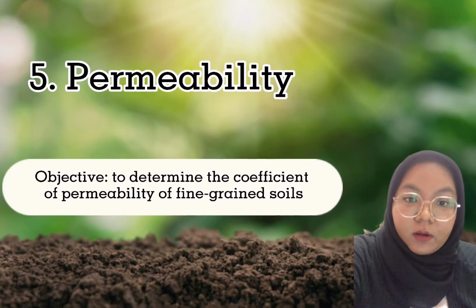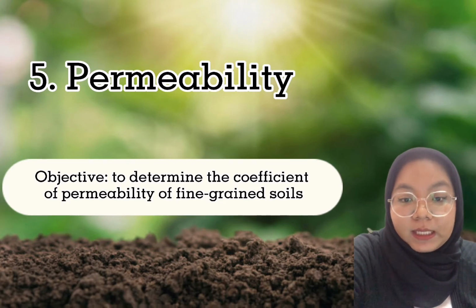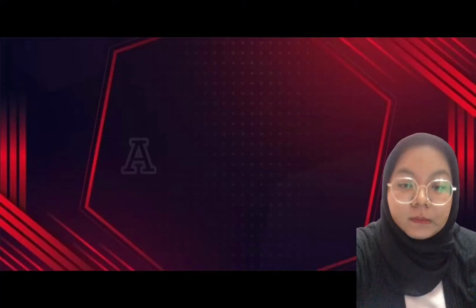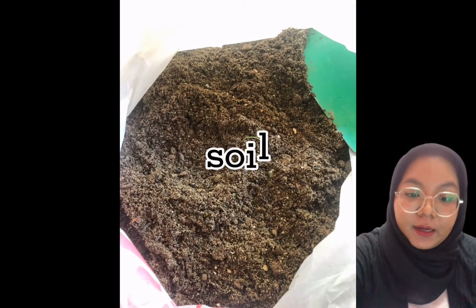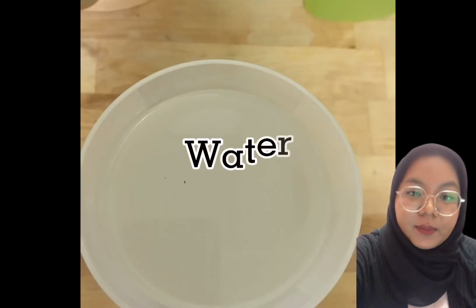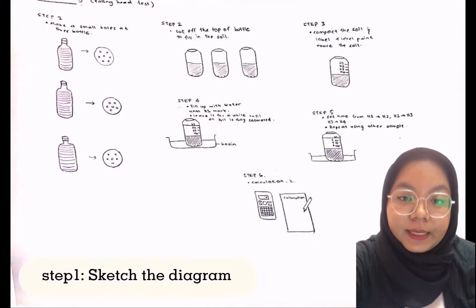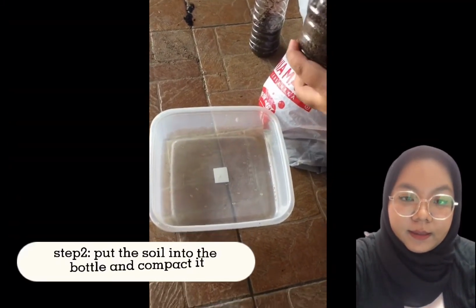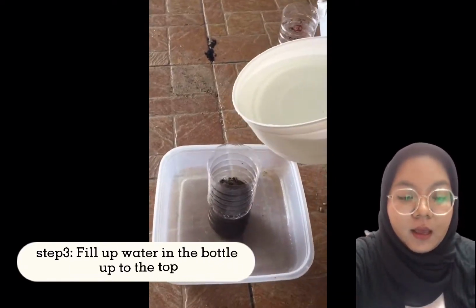The objective of the experiment is to determine the coefficient of permeability of fine-grained soil. The apparatus that I use: soil, basin, water, plastic bottle with hole at the bottom. For the first step, sketch the diagram on how I conduct the experiment. Second, put the soil into the bottle and compact it.